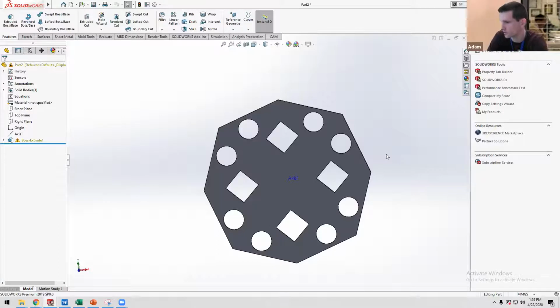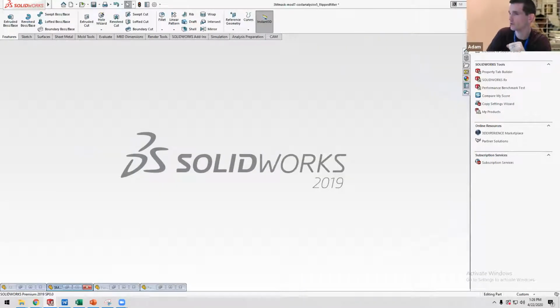If you have geometry that's the same thickness all over, this is the fastest way to prototype something that's flat sheet based. Laser cutters are also extremely powerful in terms of the versatility of the feature size that they can cut. We've cut holes down to 250 microns. I bet we can go smaller. That's just what I tried recently, but extremely tiny holes. And that's probably based on the thickness of material that you're cutting and how rapidly it melts. But that was in paper.